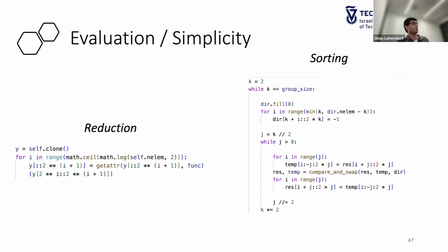And here, essentially, we're utilizing the ability to perform move operations independently. Whenever you want to perform move operations using the H tree, you only need to specify 2 different addressing. For example, I can say, give me all even elements, give me all odd elements. And if I request an addition between the 2 of them, the development library on its own recognizes that they're not aligned. It performs a shift operation to align them using the H tree to move data when necessary, and then performs that operation for you. Which means that to perform logarithmic reduction using an H tree in log of n time, all you need is a single for loop, and to do each time an addition with a different function.